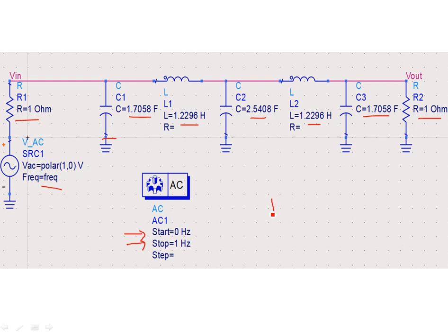We know what to expect: the 0.5 dB ripple at 1 over 2 pi, which is about 0.159, around 0.16 hertz. It's not the half-power point, but where the last 0.5 dB ripple occurs. Let me put this on. So this is the point where we get the last 0.5 dB ripple, and I'm saying this because this is what the table says.